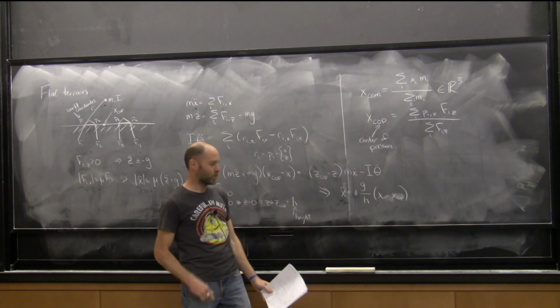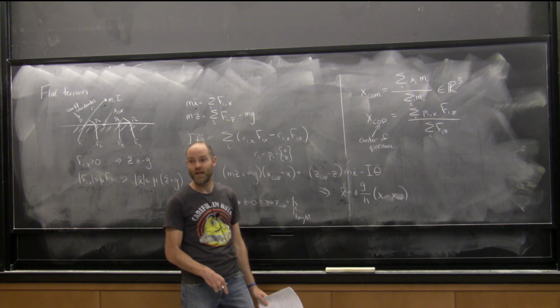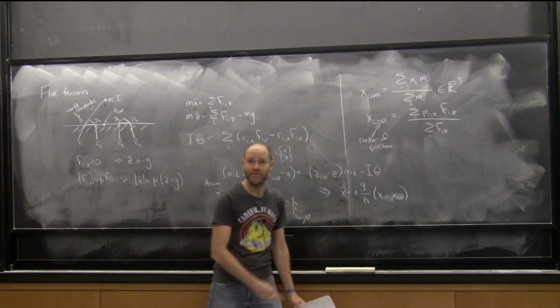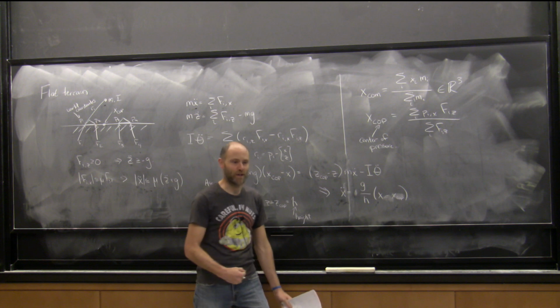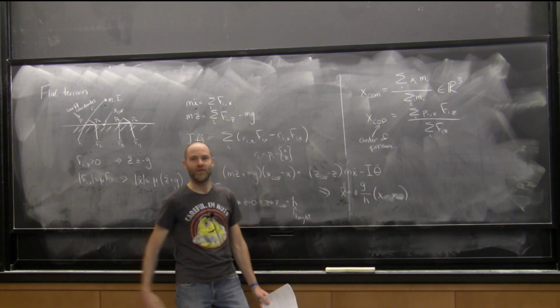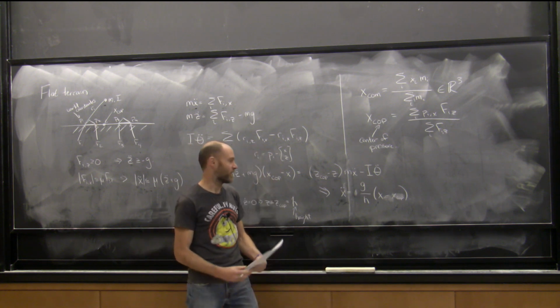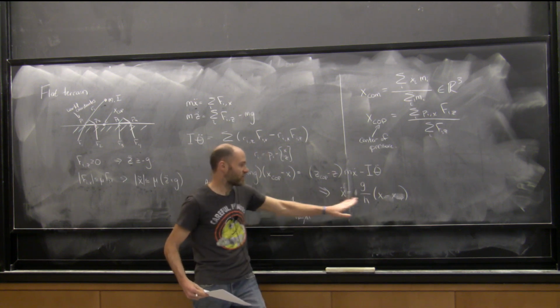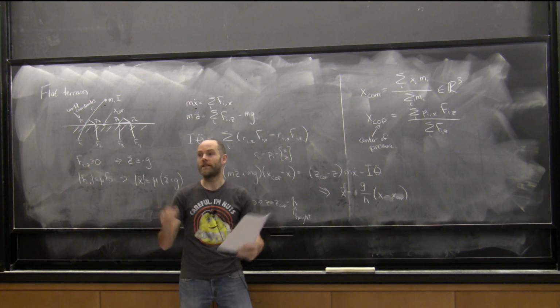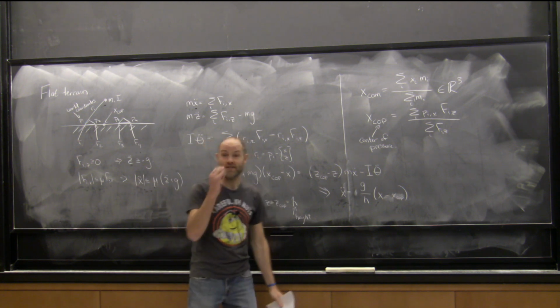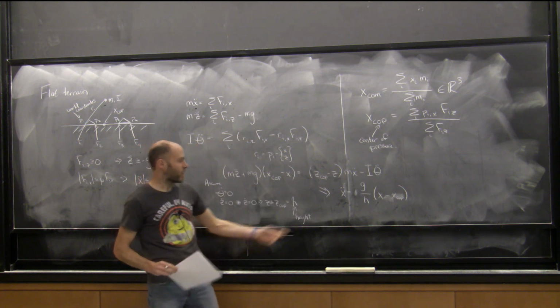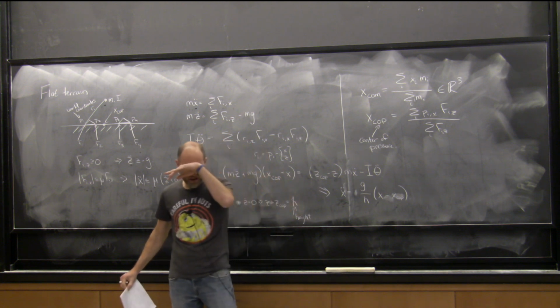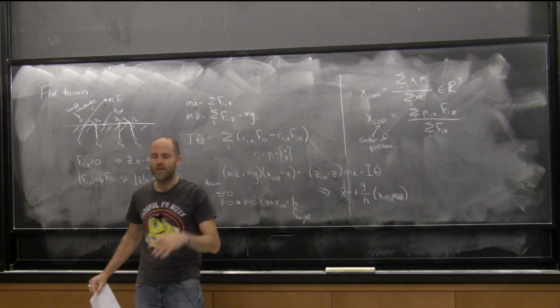So if you were to leave your center of pressure in a location, then you'd tend to fall down. And similarly, to regulate, you might have to throw your center of pressure away in order to come back. Okay, because the signs are a little wonky, but the center of mass and center of pressure are completely linked. This one, I mean, I knew the equation, but it took me a long time to realize how important that was.